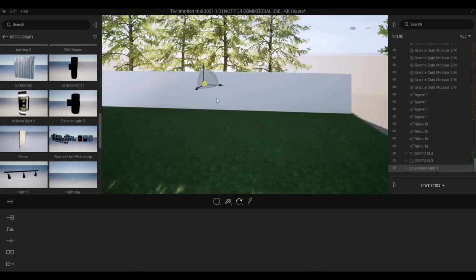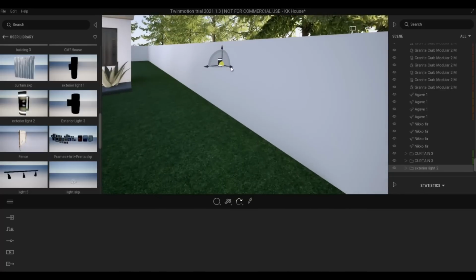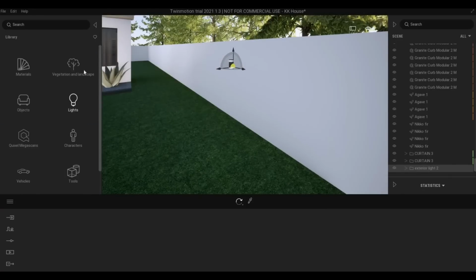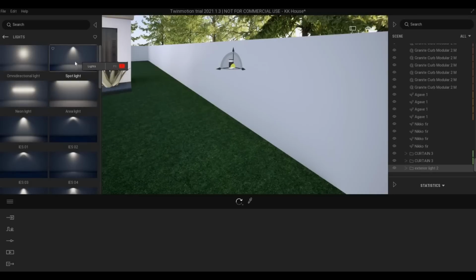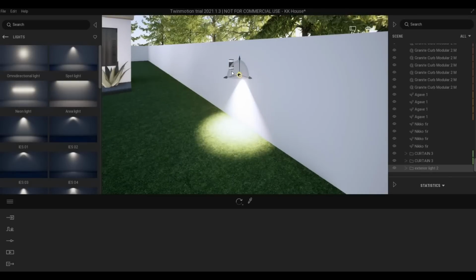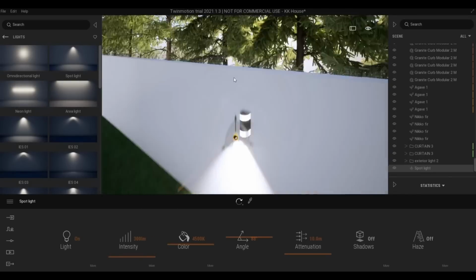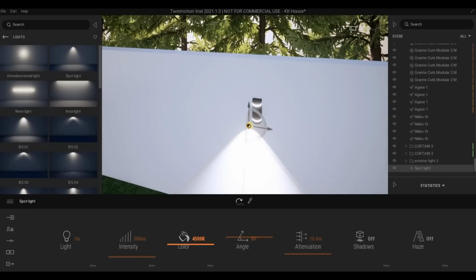So probably I'm gonna add it everything. But before I add this, make sure to add the light so that you could select them all together. This one I'm gonna put it at 10, the intensity of the light, and then the color, yellowish color.